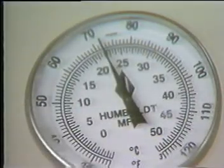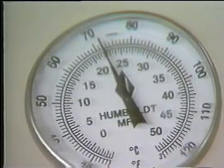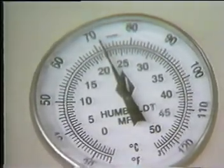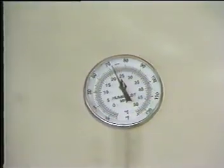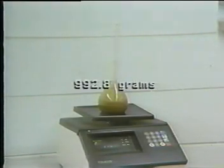The temperature of the water and test sample should be 73.4 degrees Fahrenheit plus or minus 3 degrees. Adjust it, if necessary, by immersion in circulating water. Bring the water level in the flask to its calibrated capacity and determine the total weight of the flask, test specimen, and water. Record this and all other weights to the nearest 1/10 of a gram. Our total weight is 992.8 grams.